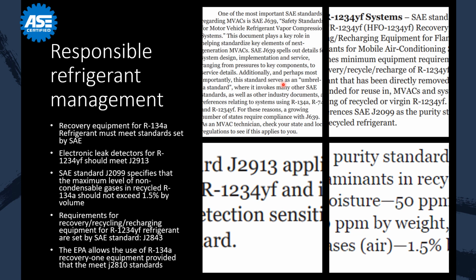I don't know all the standards, but it's important for you to study them a little bit or get to know some of these. If I ask you who sets the standard for R134A, you should know that it's SAE. If I ask you about electronic leak detectors for 1234YF, you should know that that's standard J2913. You know what I'm saying? So you have to at least understand the ones that you're going to be tested on for the exam.